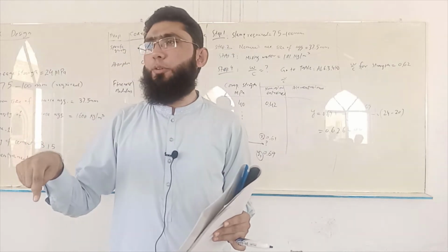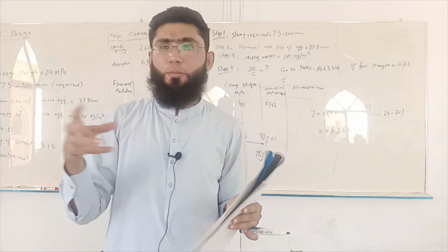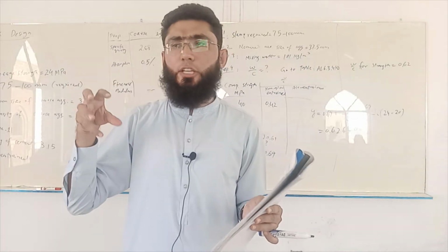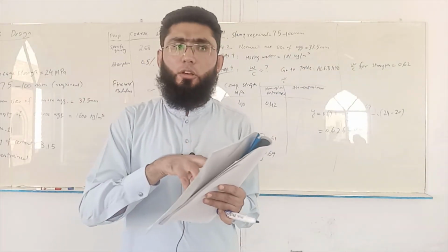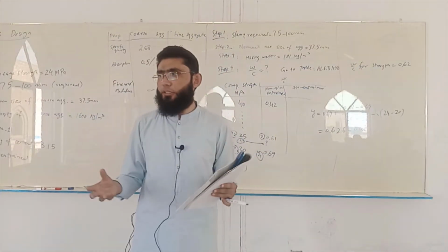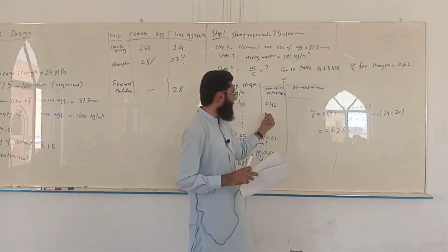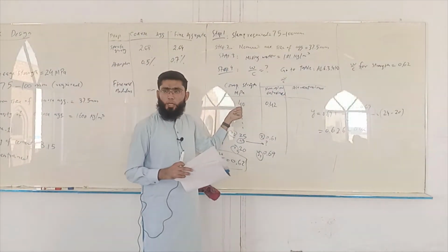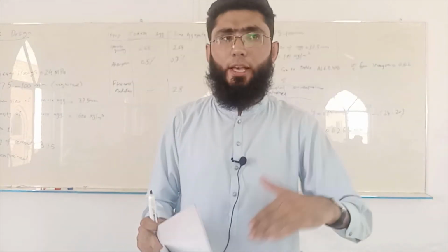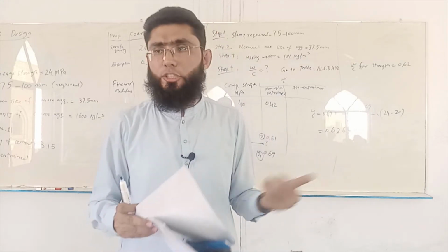And more pores in the cement paste actually means that the concrete is going to be more porous, and that means the sulfates, the chlorides, and any attacking material has a better chance of penetrating the concrete. So you have more durability risks involved. So a lower water cement ratio means higher strength as well as higher durability. Generally speaking, all the durability has to do with a lot of other factors as well, but this is the general rule we're going to follow.